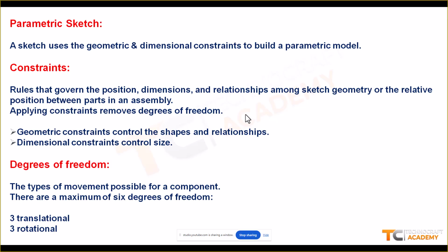Is it a fully constrained or fully parametric model? No. If you only have the geometrical constraints, it cannot be. You need to define the dimensions for that. Let's say I'll define 50 mm for the bottom length, the width. For the height, I'll define 25. Now I need to constrain it to the axis origin, 0, 0.